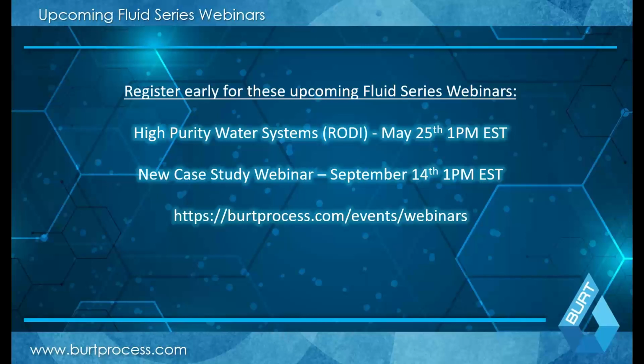Can a single stage system be used for very acidic conditions, or would you recommend a multiple stage system? It can, depending on how the system is utilized. For example, a lot of our ACS systems are single stage, and they can do that because you have that recirculation in other types of conditions. That being said, when you don't have some of those additional features, you may want to go to a two-stage system depending upon the nature of your waste and what your flow rate is. The bigger the flow rate, the more I'd move away from utilizing a single-stage pH system.